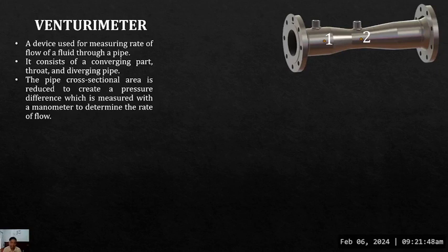No? Kasi magbabalance yung velocity tsaka pressure head. So, kapag lumalaki ang velocity head natin, yung pressure head naman mababawasan. So, magkakaroon ng pressure difference sa point 1 tsaka sa point 2. Kukumputin natin yan, using yung concept ng static pressure.